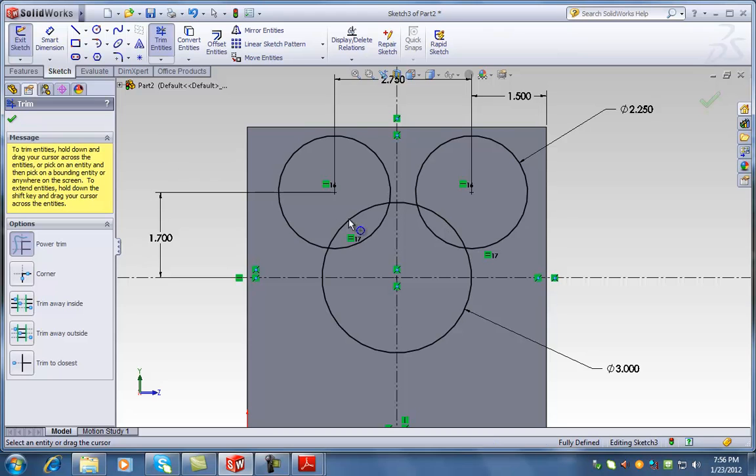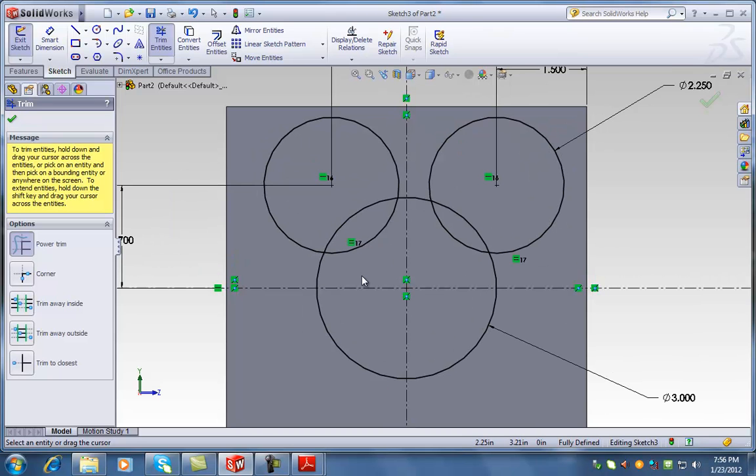So look what I'm doing before you start doing it. I'm going to start in an empty spot here. I'm going to click and hold. This is the only option where you actually click and keep clicking. I'm going to move my mouse. Do you see this white path behind me? This is basically where it's cutting. But since it's not crossing any line, that means it's not going to cut it. But notice what happens when I cross this line. Snap. So it's going to snap it to the nearest point.